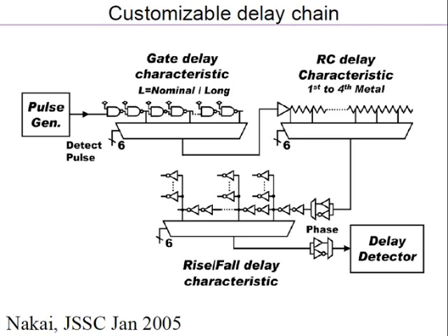The problem is that if you change the design, maybe the same design before tape out, you realize there is some issue. You have to make some change. The critical path could change very well. So till the last minute, you don't know exactly which is the critical path. So even the critical path model will have to be adapted like that.